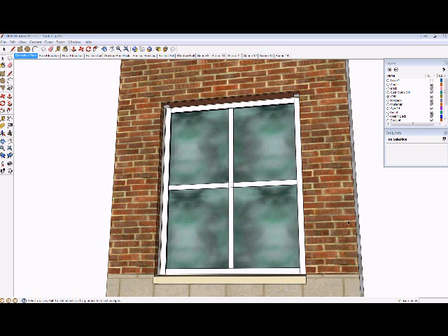Okay, as you can see here, I've switched over to my SketchUp model, which is a tool that we use to do these 3D virtual mockups. And you can see that I have an elevation of a window here that is on a project where we're actually going to be removing the finishes around the window and replacing the waterproofing system behind it in order to alleviate some leaks around these windows. So we went ahead and modeled this system in 3 dimensions. You'll see the elevation view here.